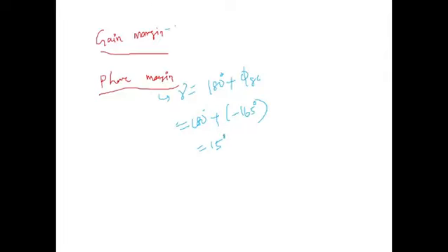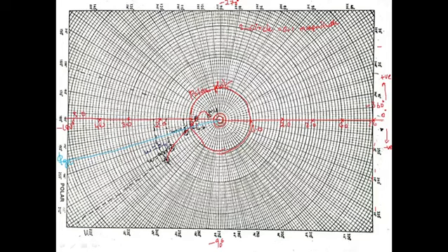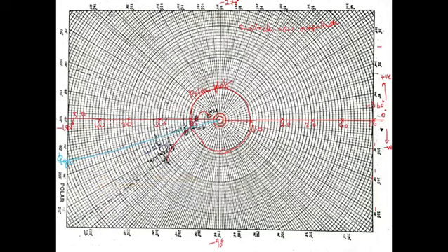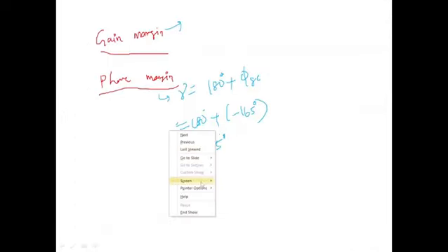That's it. Now, if you want to find the gain margin, what you have to do is look at where this polar plot and your real axis, meaning this magnitude axis, intersect at one point. It is intersecting at minus 180 degrees, right? What is the point? That point is 0.7 here. So here the value is 0.7, where your polar plot intersects with minus 180 degrees. The value is 0.7, right? So now the value is 0.7.